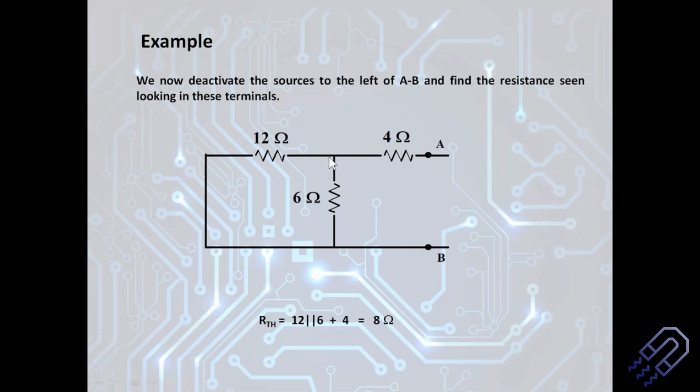So at this particular principal node, you see that the current gets divided. Some part will flow along this and some part will go along this. Where do you get that current? It's not that you're getting a current, you're just imagining it, because whenever you are trying to understand whether a resistance is in series or parallel, if it has the same current throughout, it will be in series, but if the current gets divided, they are in parallel. Okay, so that is the basic idea. That's why I'm explaining it in this way.